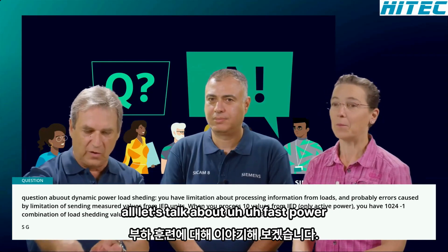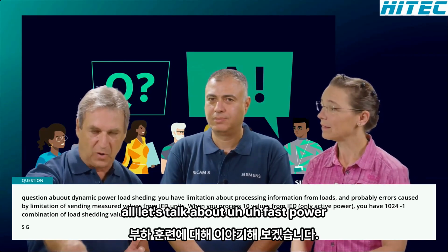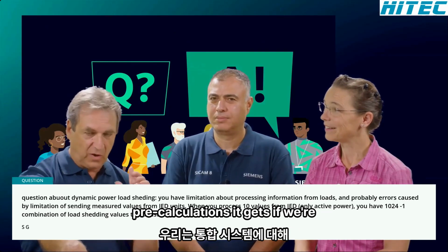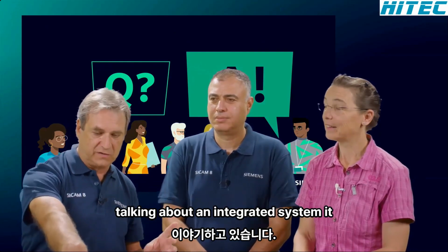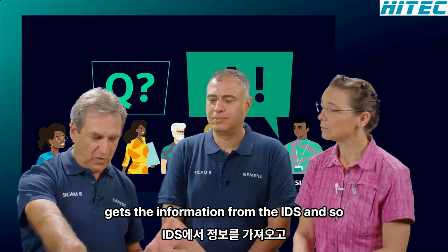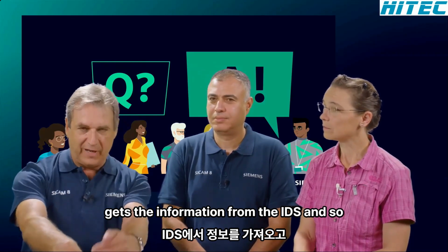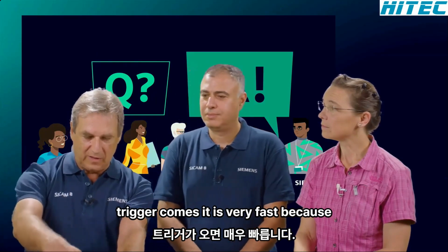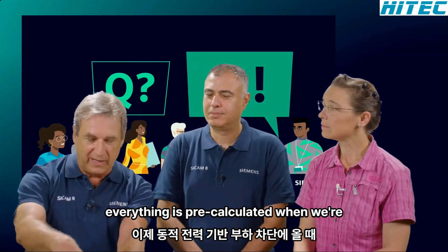So let's talk about fast power-based load shedding. It makes pre-calculations. If you're talking about an integrated system, it gets the information from the IEDs and so on, pre-calculates it, and then when a trigger comes, it is very fast because everything is pre-calculated.